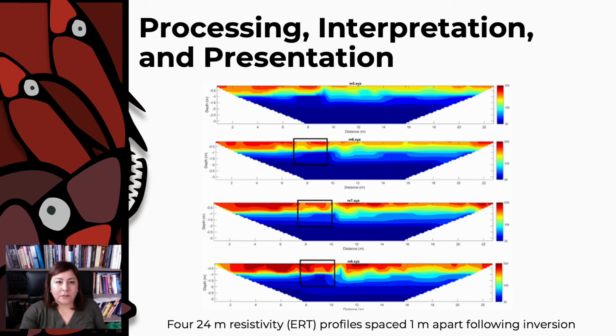Once the resistivity survey is complete, the data needs to be processed in computer software that generates plots and profiles for interpretation and presentation. File outputs are often XYZ files in ASCII format. Like other geophysical techniques, data processing is usually undertaken to reduce noise or interference and improve interpretability. Data can be presented and processed in 1D, 2D, or 3D forms.